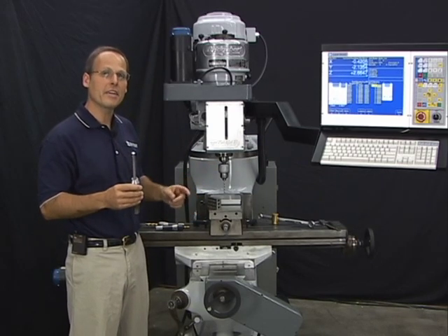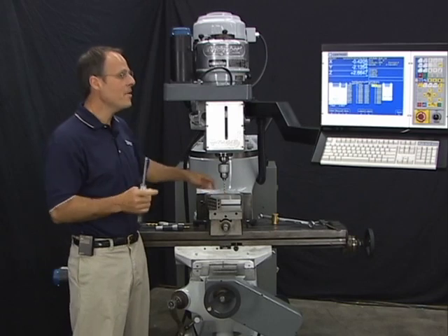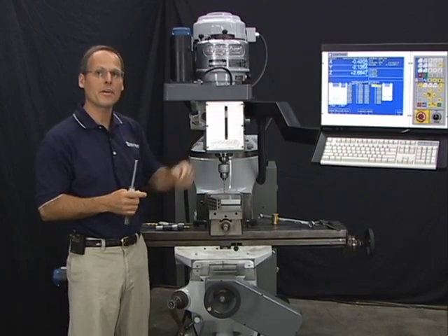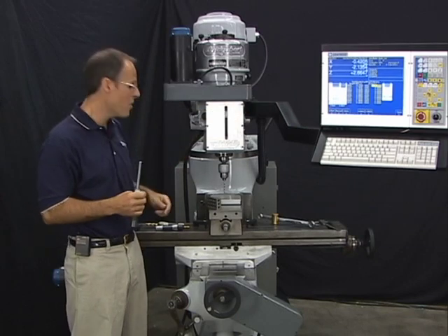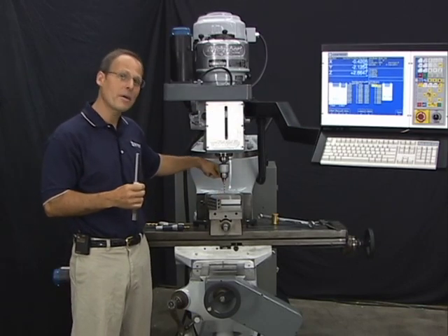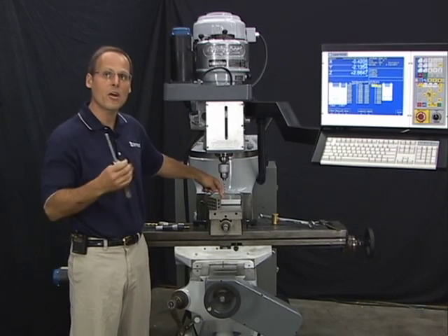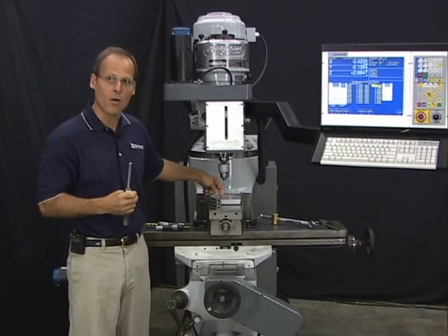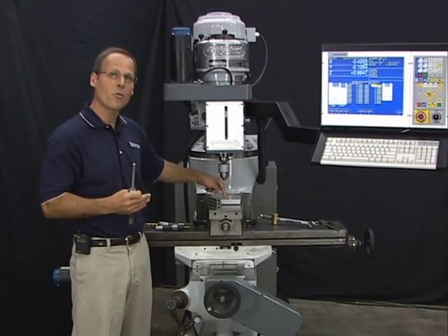What's great then, for setting your part zeros for all those different parts, I pick any one tool that's set up in the tool library. It doesn't matter which one. Any tool set up in the tool library to set my work coordinate, my part zero, and then all the other tools in the tool library are automatically set to that 0. I don't have to individually touch each tool off the top of the work.